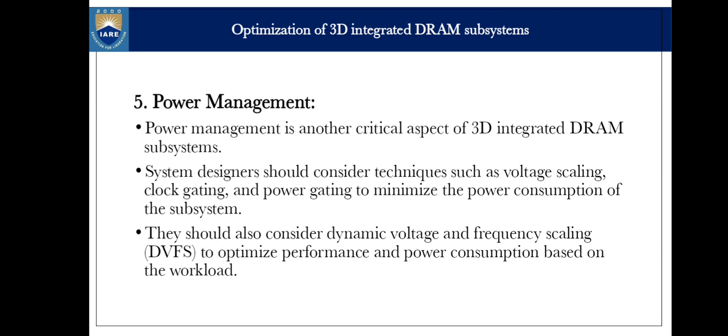Power management. Power management is another critical aspect of 3D integrated DRAM subsystems. System designers should consider techniques such as voltage scaling, clock gating, and power gating to minimize the power consumption of the subsystem. They should also consider dynamic voltage and frequency scaling (DVFS) to optimize the performance and power consumption based on the workload.